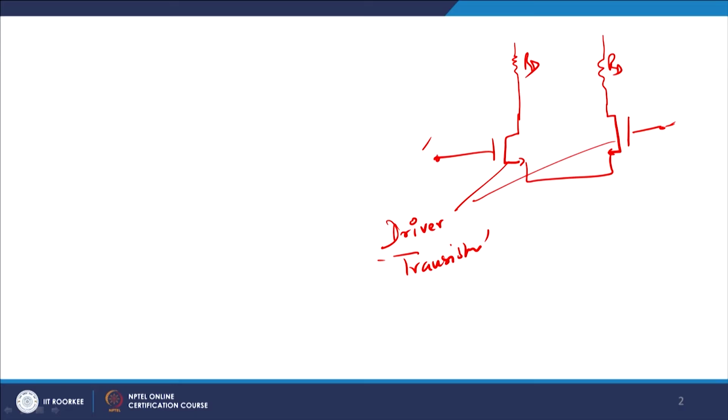This is the RD value, but in reality, when you do it on an IC or on a chip, when you want to fabricate it, these resistances will be performed by MOS devices. Typically if you use a PMOS device here, you have a larger resistance being offered at this particular point. We will see as we move along how it works out, but typically you have learned that the gain is given as gm times RD.